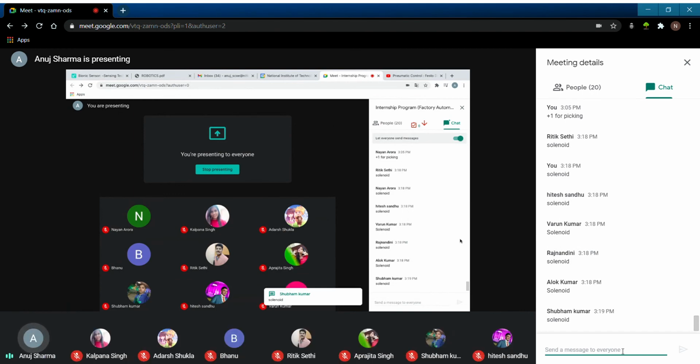It is also actuating a particular DCV, and the solenoid gets excited by getting an output from a relay, which gets excited through the signal that it gets from the PLC. The PLC gives a particular signal for the excitement by a certain logic, and that logic can be activated through a particular sequence, whether it is from actuation through a switch or sensor or anything else.